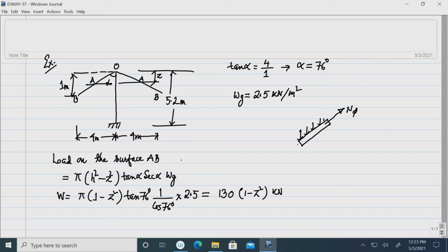So, therefore, no stress is there, and you can see that the total vertical component of the load n phi has to be balanced by the vertical load acting on this portion. Now, using this, n phi cos alpha is the total vertical component of n phi, multiplied by the circumference of the circle at this level.